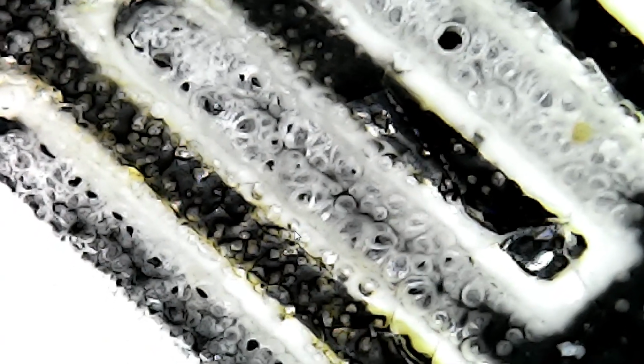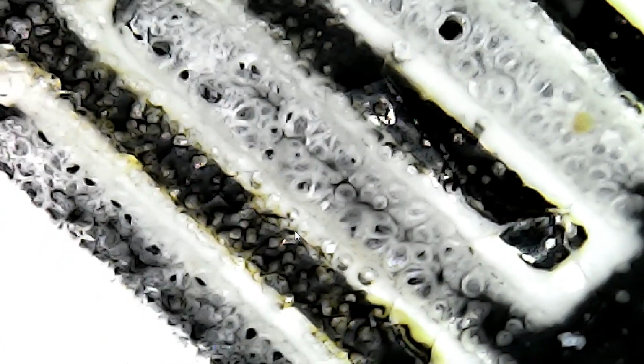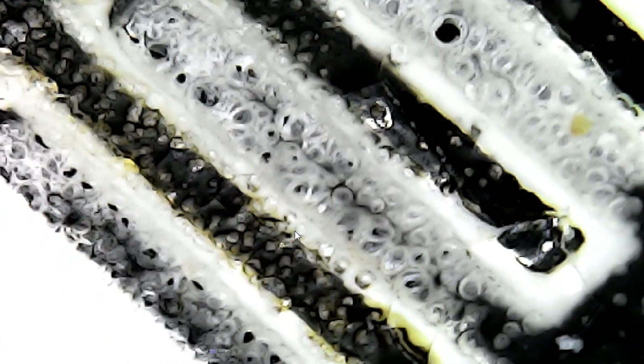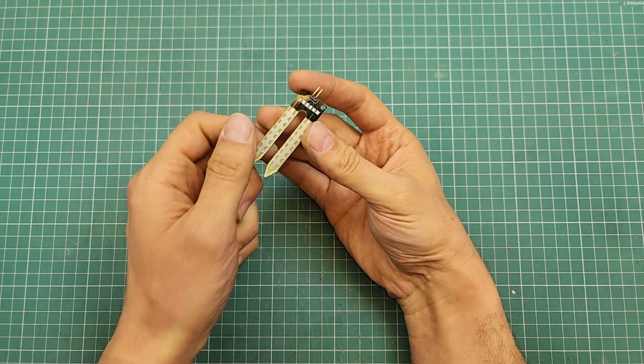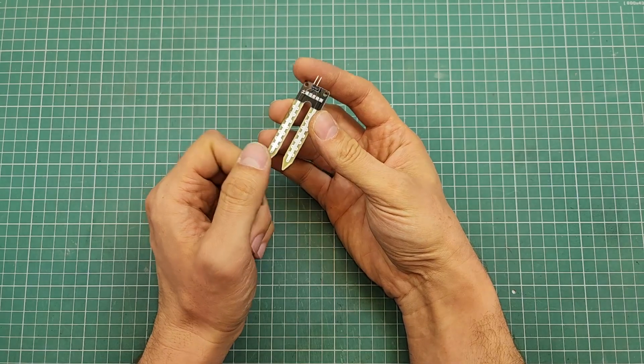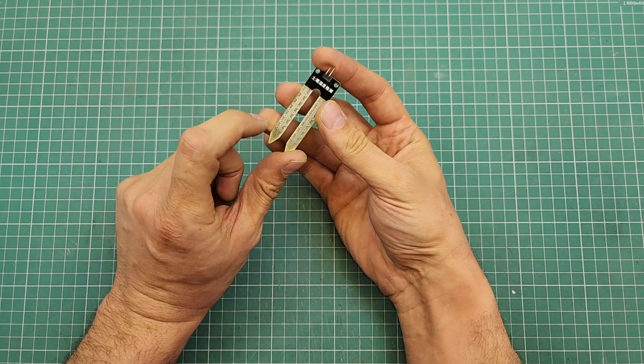When the air humidity increases, a connection is created between these two electrodes, and as the humidity gets higher and higher, the connection between these two electrodes becomes stronger, and that's enough for us to use this component as a sensor. Other sensors have the exact same system. For example, the working principle of the soil moisture sensor is similar to the air humidity sensor.